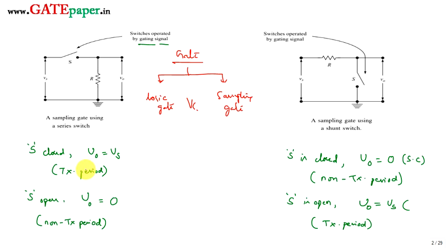A logic gate is totally used in digital circuits. So the inputs as well as outputs are going to be digital. Either pulses or voltage levels, only two levels are possible, either high level or low level. That is, a range of voltage which specifies high and a range of voltage which specifies low.